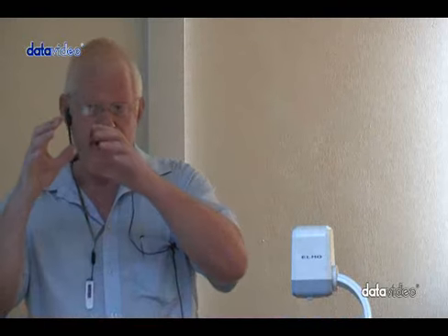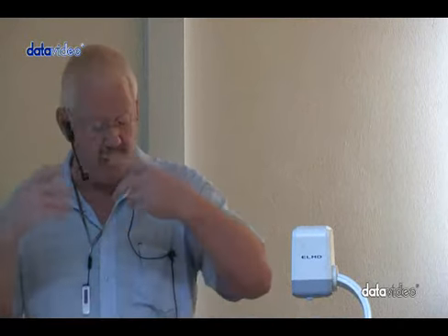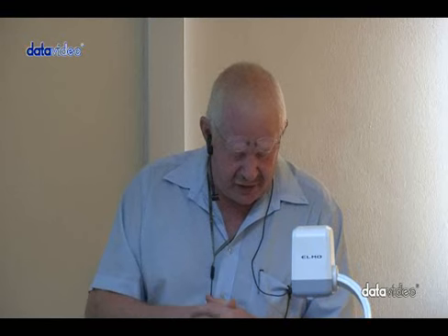So remember, underneath the DC analysis, you will calculate the value of IE, but I need that value to calculate the value of r'e. So if I go and have a look at example 6.2, where they use this formula in an example, determine the r'e of a transistor that is operating with a DC emitter current of 2 milliamps. So the 2 milliamps has already been calculated. I just put 2 milliamps into this formula. I get a value in this specific case of 12.5 ohms, which brings me to the next point.